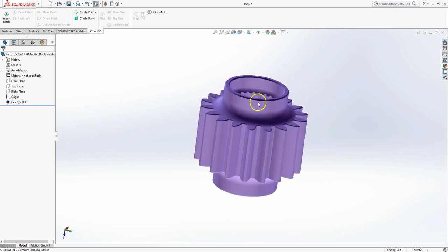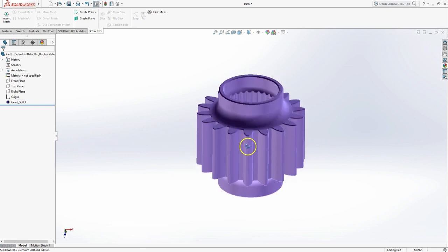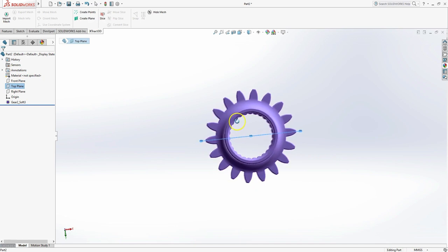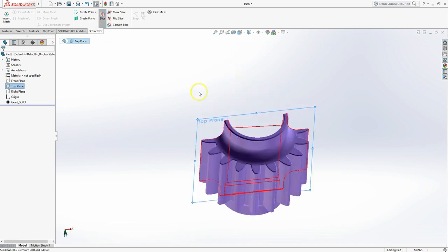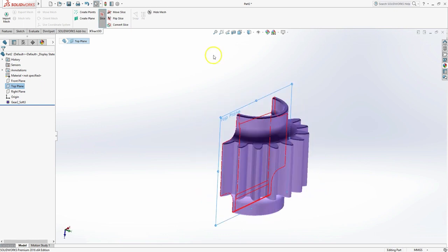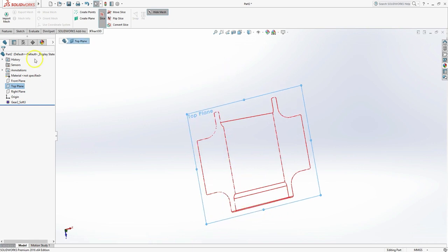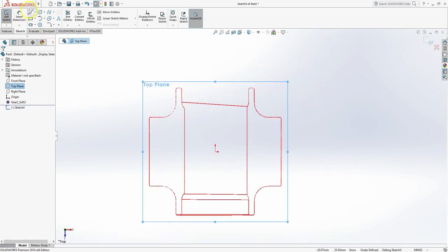First thing I'm going to do is create the exterior 3D portion of it, the revolve function, or the revolve features here. So I'm going to pick a plane right there down the middle, and we're going to use the slice function to slice through the 3D scan just like that. And I'm going to hide the mesh. So I've got a reference curve of the boundary of the mesh shown right there, and I'm going to go ahead and use that same plane to create a sketch in SOLIDWORKS.